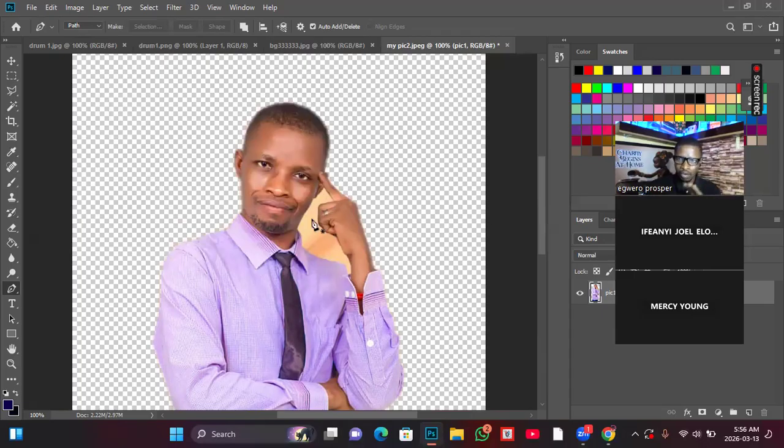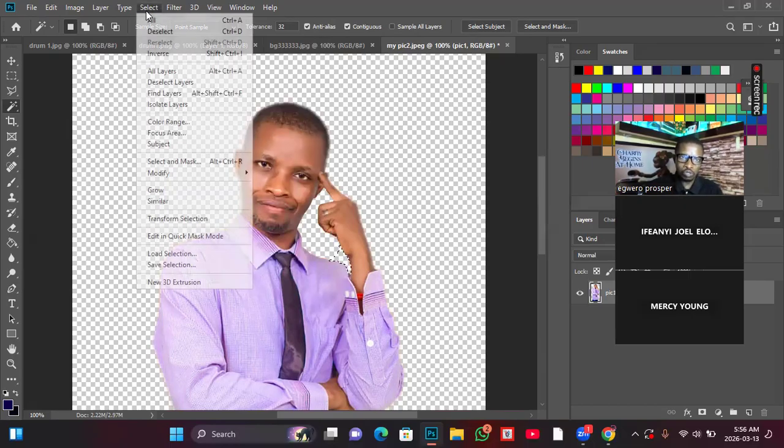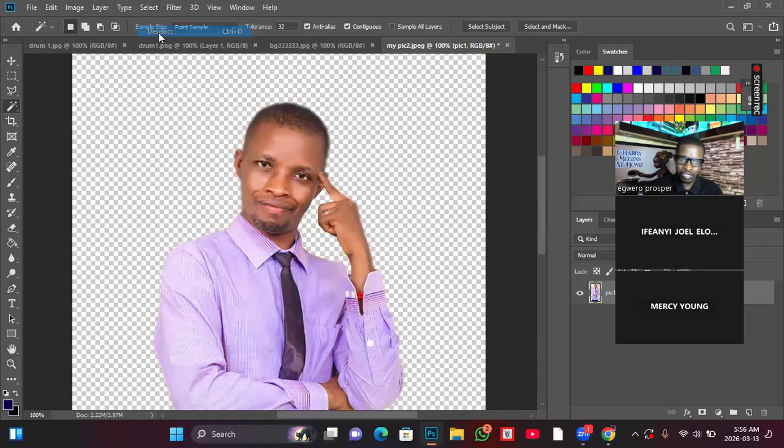So the same logic I want to apply here. I will just click here and touch this place. You can see the way it highlights the area that you click, the color that is the same with it. So I will just press delete. I've removed that one. I will now click here and press delete. I will now click here and press delete. Then Control D, or you go to Select and select Deselect. So now I have gotten it.